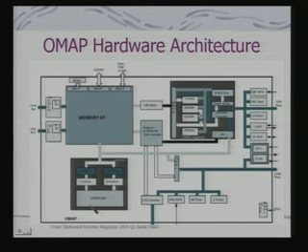In case of the ARM core, in fact ARM9 is a Harvard architecture based processor. So, you have got an instruction cache and a data cache which are separate, and then it has got its own MMUs, memory management units. Through this, this processor is using the memory interface to access external memory.